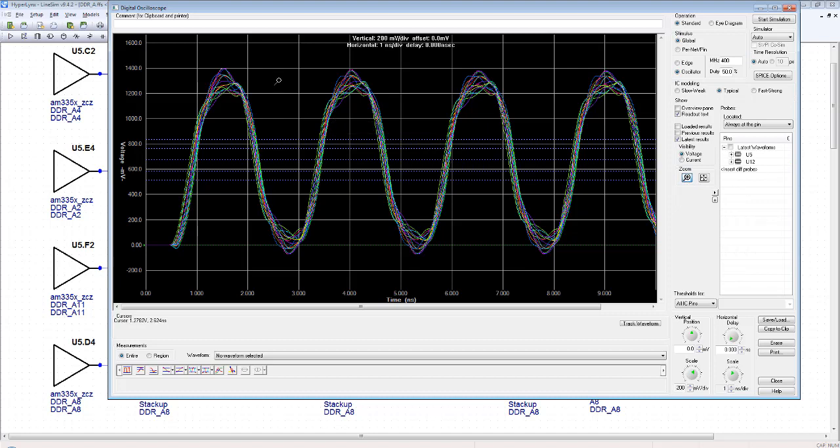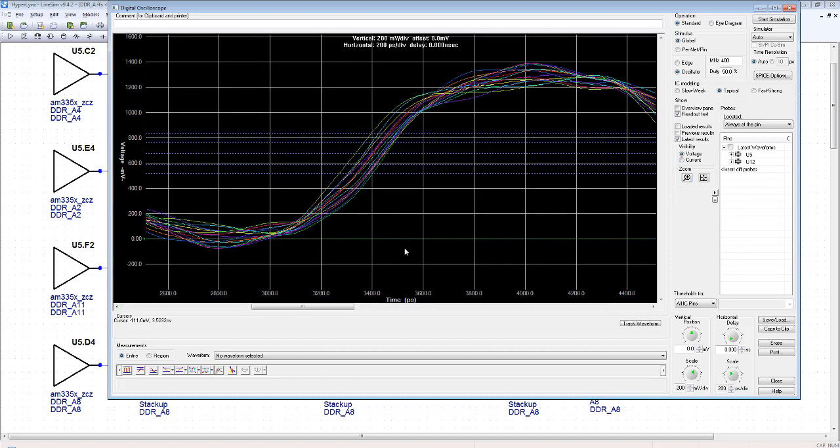And maybe zoom somewhere here, where we see all the address lines and the different arrival times at the memory chips. Now I can do a lot of things in this scope, but in this moment I'm only interested to get my fastest arrival time and my latest arrival time. We don't need to be very precise for this exercise, and we see here an amount of 135 picoseconds of skew. So why is this? We nicely matched all the address lines to about plus minus 100 micrometers, but we are getting such a huge skew.